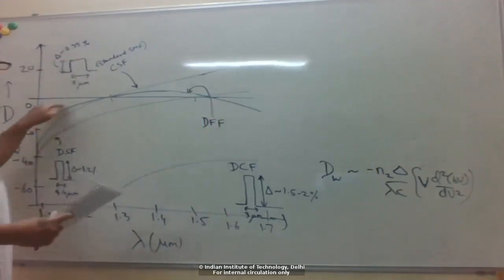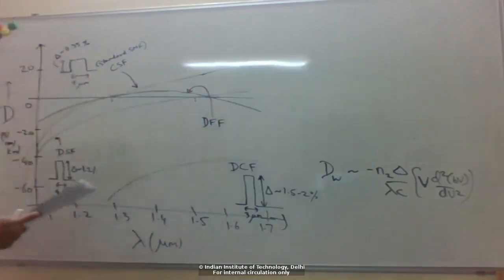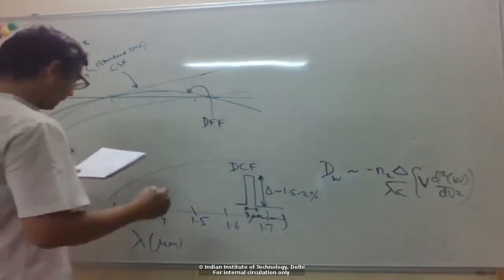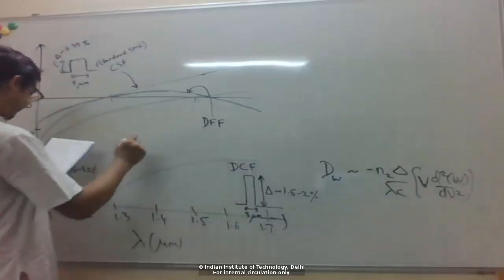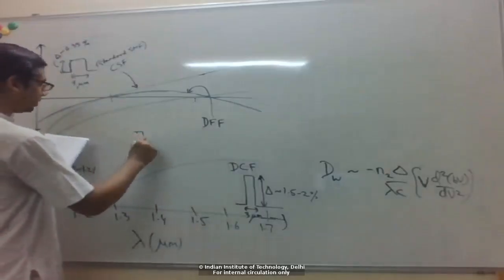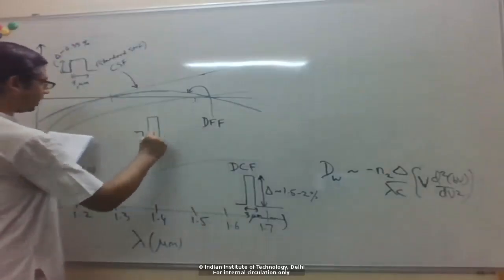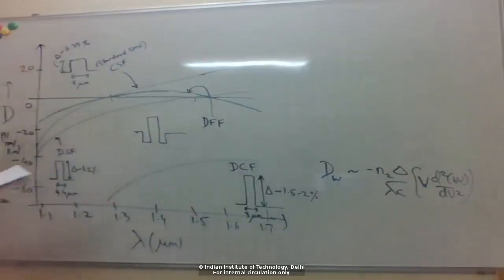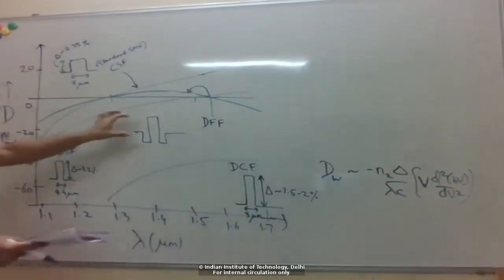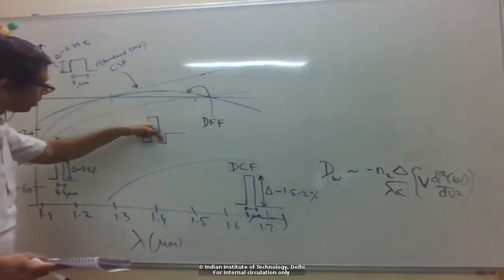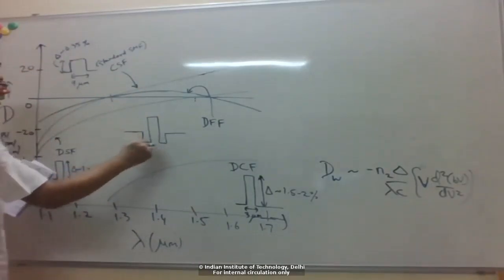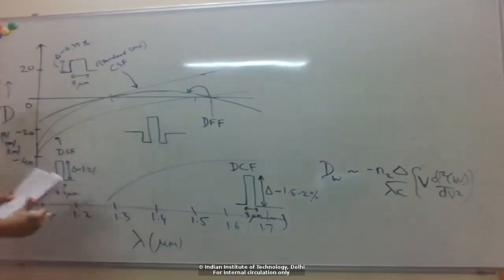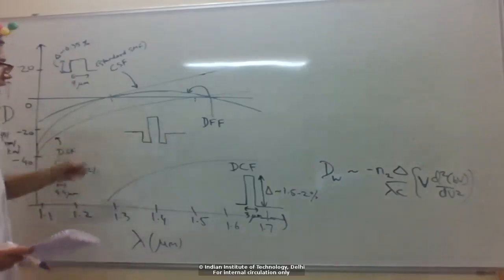Okay, and to achieve this kind of flat dispersion profile, you have to do now fancy things with the refractive index profile. So, for example, this now has a complicated refractive index profile like that. Okay. So, in the middle it's high, but then it actually goes lower than the cladding. There's a ring around the high index core which is actually lower than the cladding.